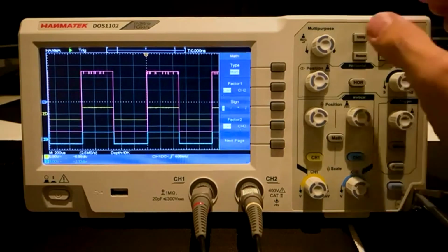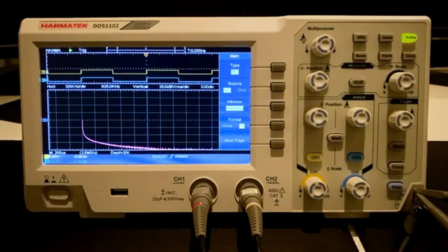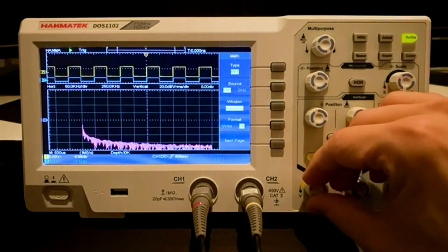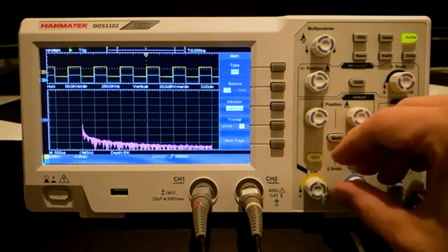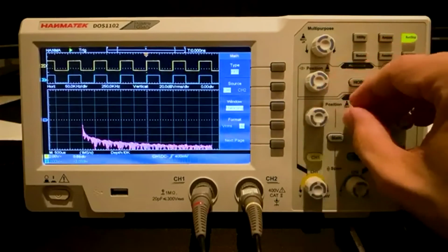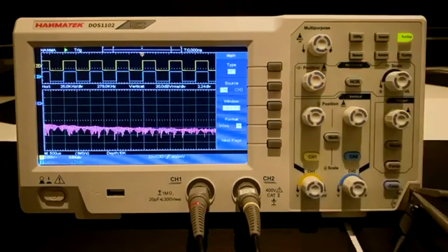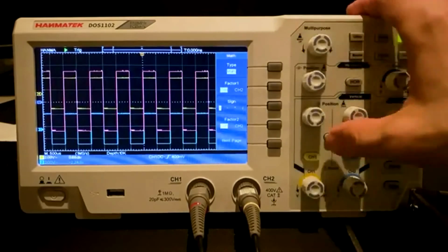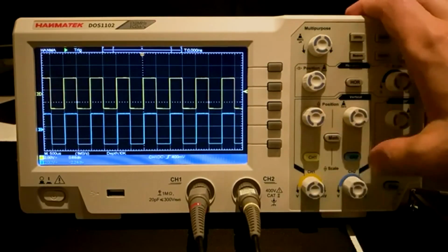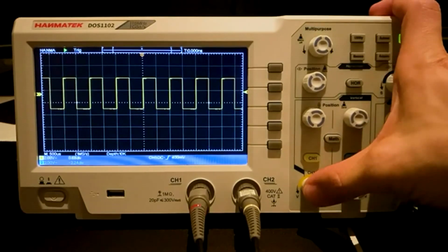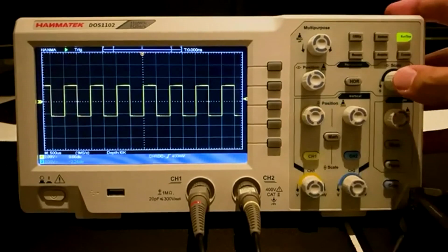The type FFT, fast Fourier transformation, is tested. The two input signals from channel 1 and channel 2 are shown on the time axis in the upper display. In the lower display, the signal from channel 1 is shown in the frequency domain. The math mode is exited by pressing the math button. Channel 2 is deactivated. The channel 1 signal is automatically aligned by pressing the position button.